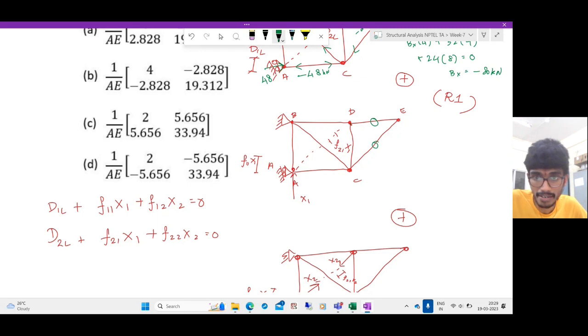Again, coming to this joint, you have something at perpendicular, so if you enforce equilibrium equations, this is 0, this is 0. Coming to this joint, you again have two non-collinear members subjected to no loads, so these two are also zero force members. Finally, the only member that is stressed is this.